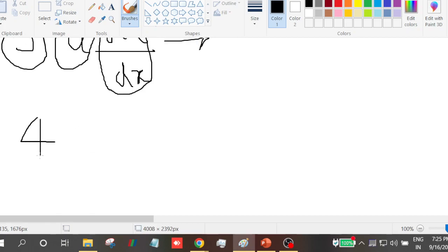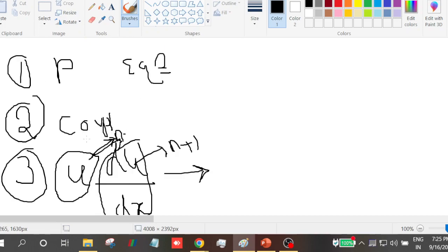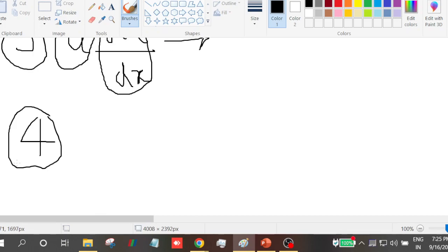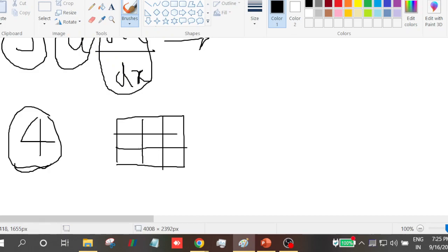Okay, now the other main challenge is the fourth challenge: whenever you go with our normal control volumes and the grid arrangement called collocated grid arrangement, wherein you have pressure, x velocity, y velocity at the center of this control volume, you will end up with a staggering problem, which I will explain with one of the problems in the tutorials. We have a problem which can exactly tell more about this.